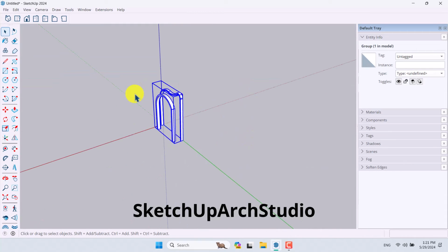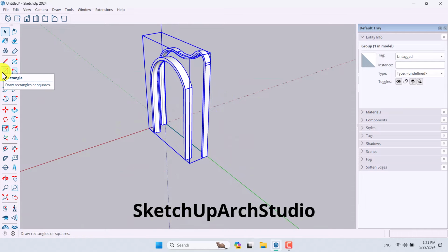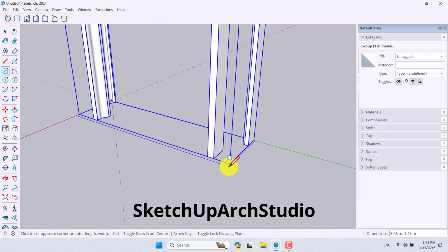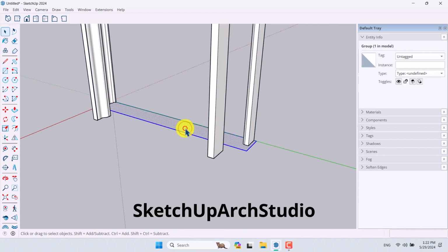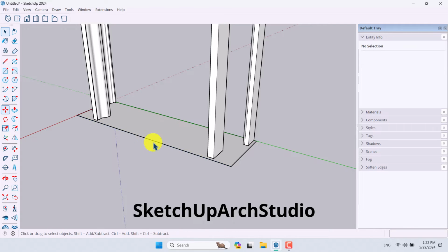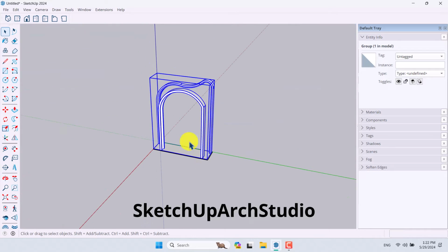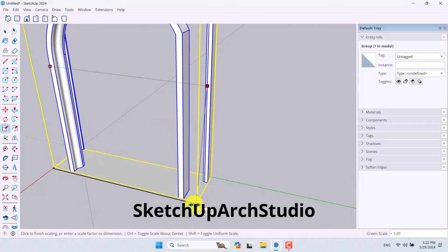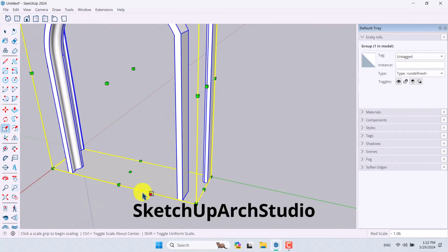in here. So now you need to draw another rectangle for resizing your main object. Draw your rectangle like that. For example, 5.10 to 0.6. Click on it. Click on this edge. Move it to this side. So click on your main object, click on the Scale option in here, rescale it completely to fit and match with this face in here.